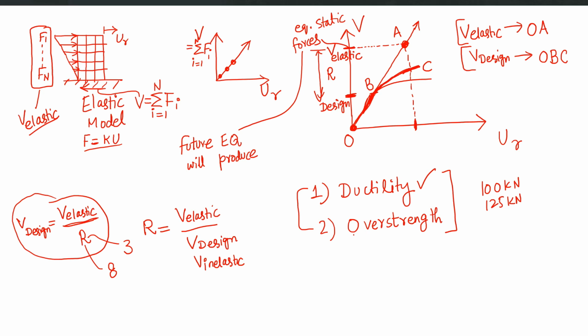or this linear time history analysis procedure. So in all three seismic design procedures, this R factor will have its role. The reason is that the computer model which is used for the purpose of seismic design is an elastic model. If we could make it nonlinear, just imagine for 1 second that we have a nonlinear computer model, then we don't need this R factor.